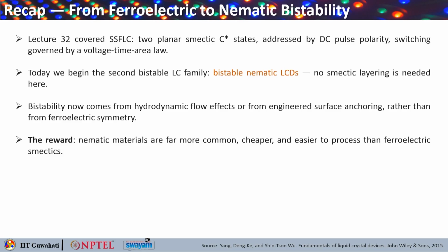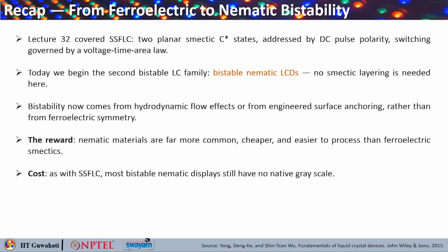The reward is that the nematic materials are far more common, cheaper and easier to process as compared to ferroelectric smectics. So cost wise, as with SSFLCs, you will see that most bistable nematic displays will also have to pay a price by not being able to provide any native grayscale. Okay, so it's basically only on off.